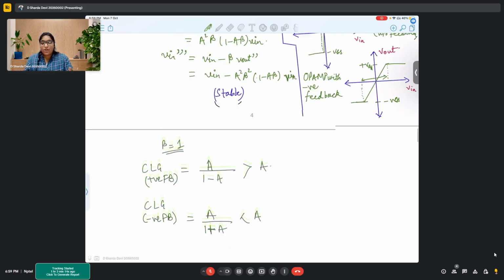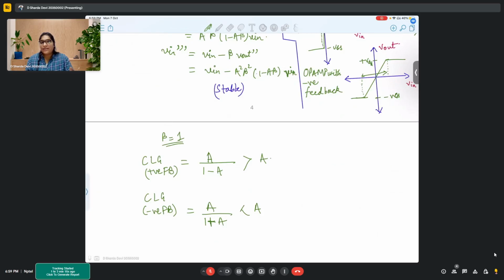We have also seen, in the differential pair, the ICMR, the input common mode range. It talks about the input ranges that are feasible for your system, and it comes from your output swing and gain analysis. That's how you utilize this information to find the range of inputs that can be provided to your circuit, because it is very important, as the signal strengths are different.